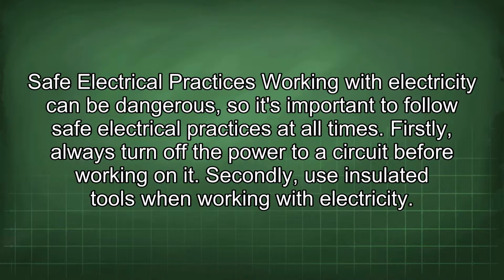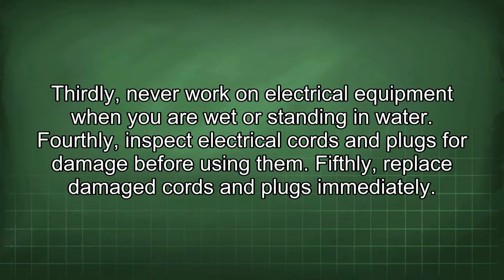Safe electrical practices. Working with electricity can be dangerous, so it's important to follow safe electrical practices at all times. Firstly, always turn off the power to a circuit before working on it. Secondly, use insulated tools when working with electricity. Thirdly, never work on electrical equipment when you are wet or standing in water. Fourthly, inspect electrical cords and plugs for damage before using them. Fifthly, replace damaged cords and plugs immediately.